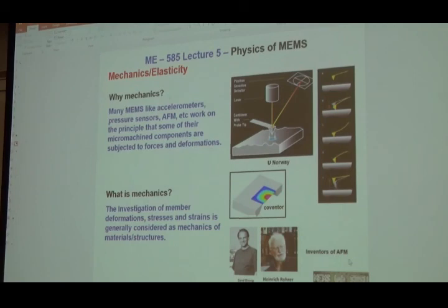So what happens is we point a laser light on top of the cantilever. As the cantilever goes and taps, and if there are features that are going up and going down, then the reflection is affected, right? So there's a position sensor, and I can read that position. Eventually, I could map that. You cannot imagine how much difference it made in a lot of areas. It's one of the monumental inventions of our time.